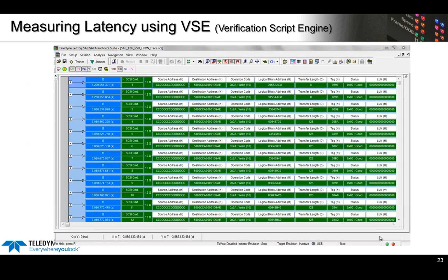Okay, so right here we're looking at a high bandwidth trace between real devices. So this is real world traffic, real host, real device, and we're basically showing the SCSI command layer. There are multiple SCSI write commands in this screen. And these are line rate captures, right, with the analyzer. So to measure latency in a trace like this, you could obviously look at each transaction and manually calculate the latency, packet to packet, command to data. But we also have several tools that can help you here.